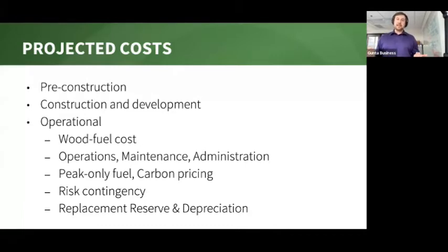And often, when these engineers come into these buildings and they have a heating system in place, anybody who's an engineer who has to cost these types of systems out or does energy auditing of buildings will already know that most heating systems in place are two to three times bigger than they need to be. And there's a lot of reasons why. These systems too are able to scale their load effectively. In biomass, it's a bit different.